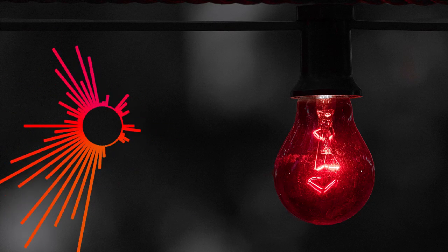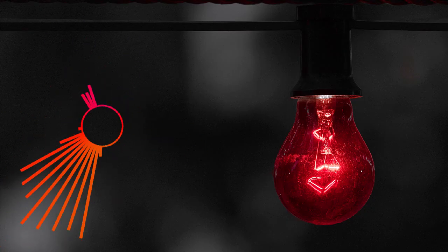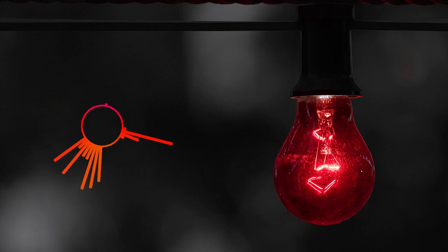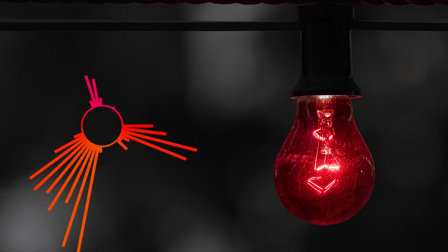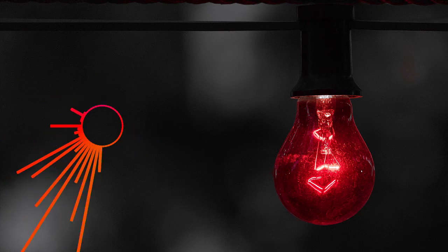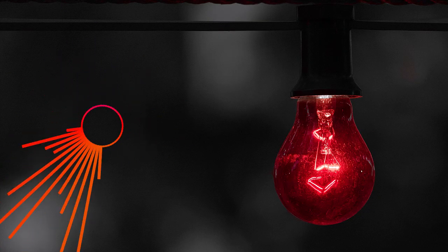As someone training to enter the electrical field, here's what you should remember. LEDs are different from traditional lighting. They're electronic, not gas or filament based. You need to consider heat management, optics, and system design. Understanding specs like lumen output, efficacy, and color rendering will help you pick the right product for the job. LED retrofits are a big part of today's electrical work, so knowing how to replace older systems with LEDs is a valuable skill.